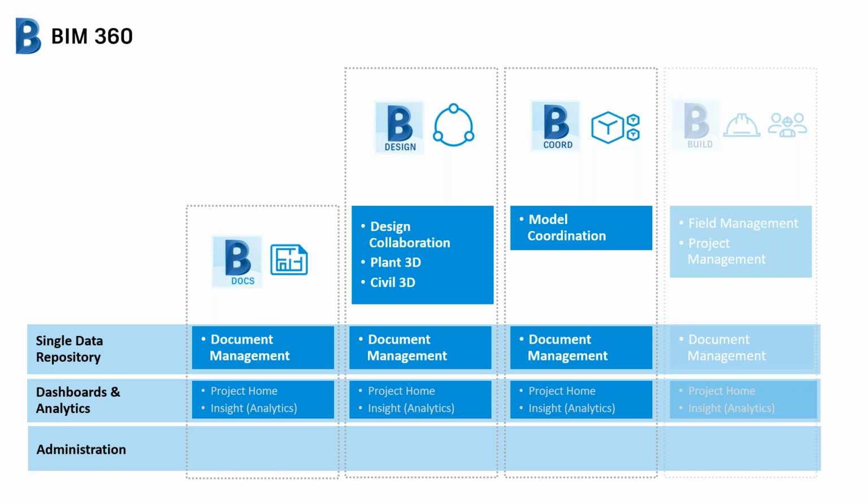Coordination spaces allows you to choose the BIM 360 Docs folder to place models from the different teams. And once you've done that and the drawings or models are in there, it automates clash detection and runs automated clash detection on these files using cloud computing resources. So there's none of your time, it just happens in the background, it's all automated.